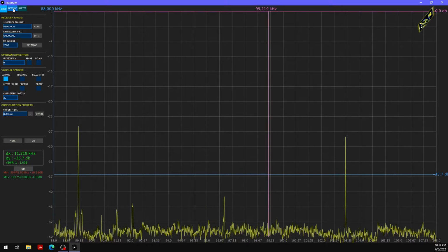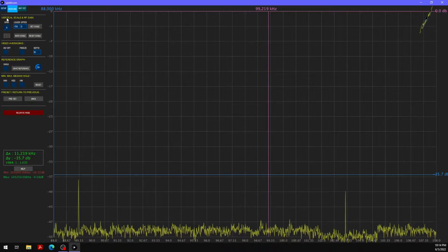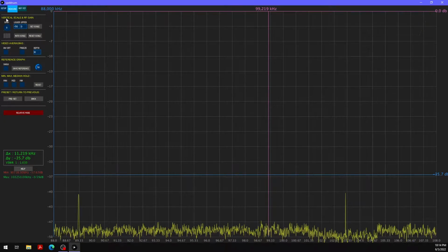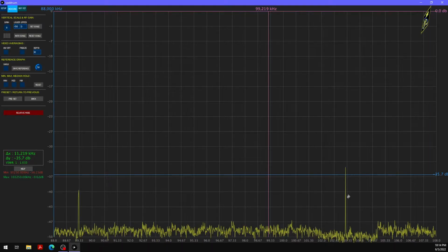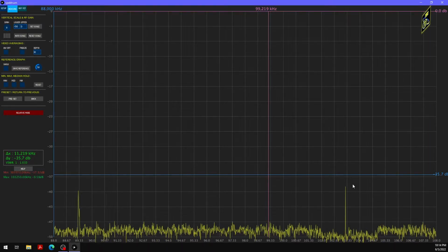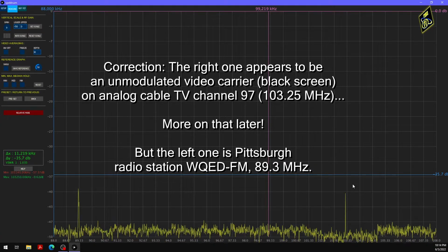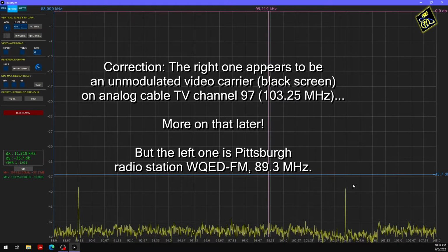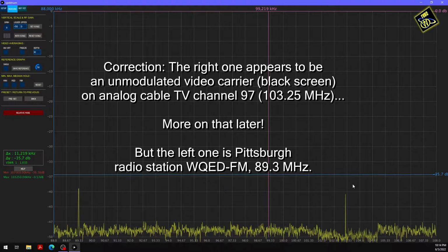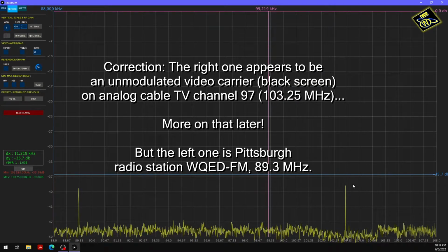And the first thing I would do is go to the Measure tab and turn this gain down to 0. What's interesting here in the FM band, I can still see what appears to be 2 carriers, and those are most likely actually FM radio stations leaking into the line a little bit, which does happen, especially given that I'm only about a mile away from some high power FM radio stations from their transmitters.